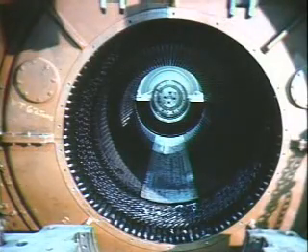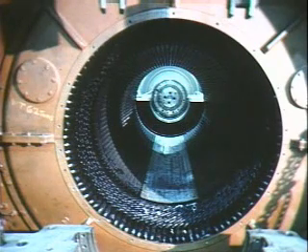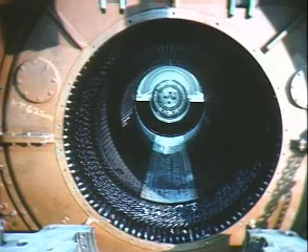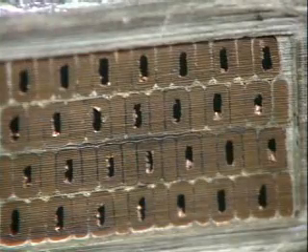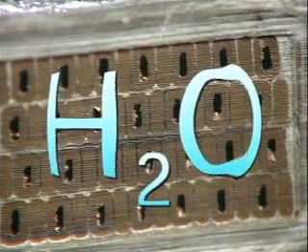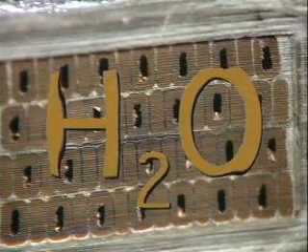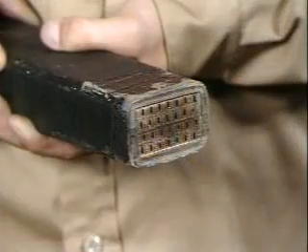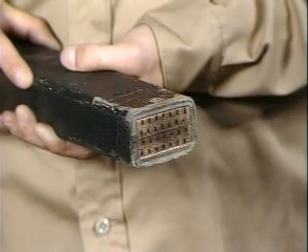The stator in a generator is made up of bars that carry current to the generator's output connections. This current flow produces a significant amount of heat, so larger hydrogen-cooled generators often have a separate cooling system to cool the stator. The stator is cooled by pure water that flows through hollow conductors inside the stator bars. Even though electricity is present, water can be used because pure water is actually a very poor conductor. It's the dissolved solids and impurities in water that cause it to conduct current. Stator cooling water is demineralized and filtered to keep it very pure and non-conductive.